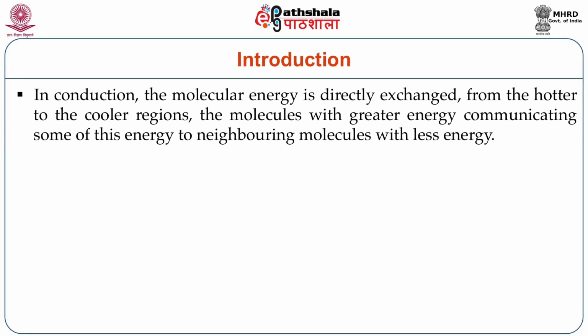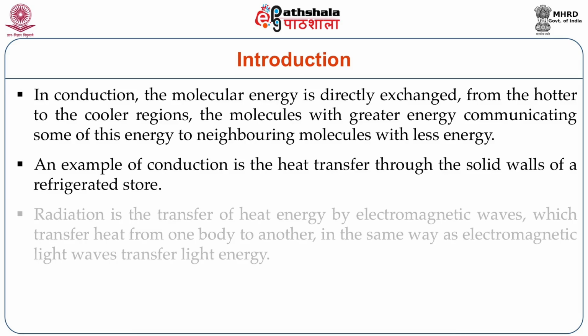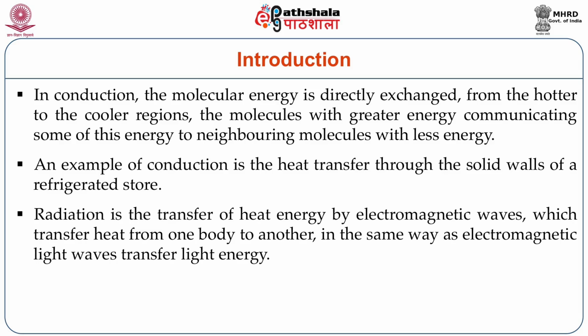First one is conduction. In conduction, the molecular energy is directly exchanged from the hotter to the cooler regions, the molecules with greater energy communicating some of this energy to the neighboring molecules with less energy. An example of conduction is heat transfer through the solid walls of a refrigerated store. After understanding conduction, let us now move forward to radiation.